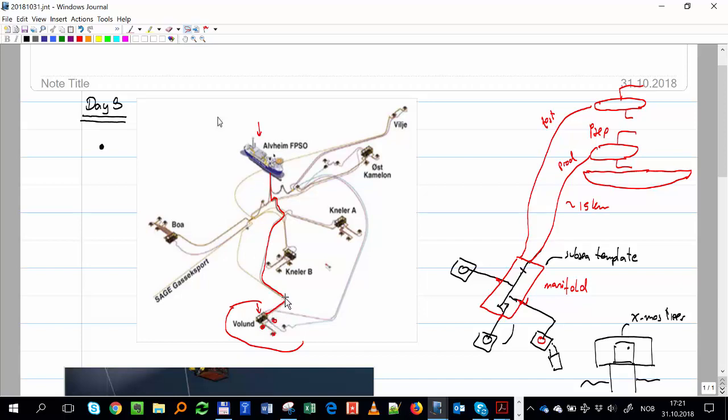So you put a line from there all the way to the FPSO. Now you don't have a subsea separator to test. This is subsea. So any separator you want to put to test, you have to put it on top of the same boat. And then you see, well, to reach that separator, I don't want to interrupt the production from all the other wells.